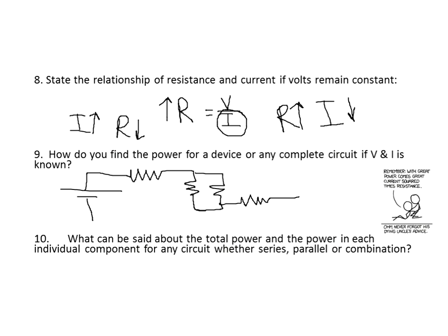I think you're getting the idea here. And what I find out is if I measure right here the current, and that's called the source current, and if I know the voltage of this, I do not care what kind of circuit it is. It could be the most complex circuit in the world. But if I know the total current and I know the total voltage, I can find the total power of any circuit. So how do I find the total power of any circuit?